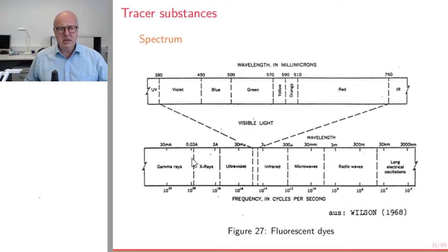And basically what we do is we just measure with light. So we need a light source. The light source is a lamp of a specific wavelength, LED, or a lamp with filters, a lamp that produces a very well-defined input and from which I actually cut a certain wavelength with a filter.